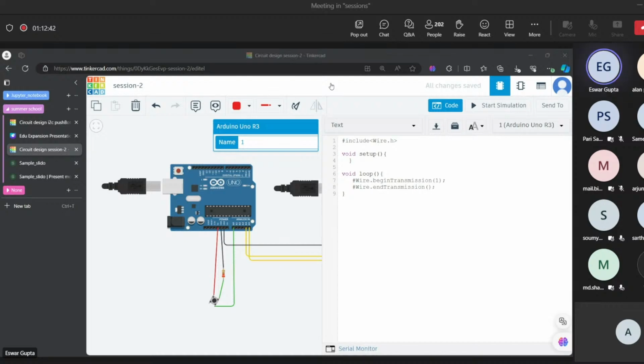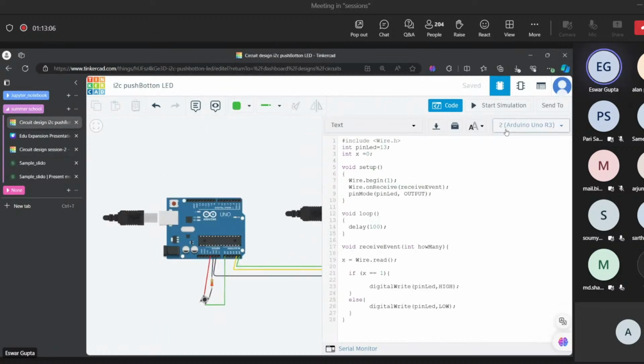Why we have connected particular terminals to particular pins in Arduino, I will explain in the code. I will get to that. Why a common ground, I had explained already. Okay. So that is hashtag include Wire.h. That library has the functions which are used for I2C communication. And once you are done with that, we will declare the remaining things.